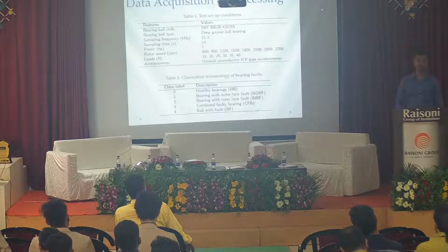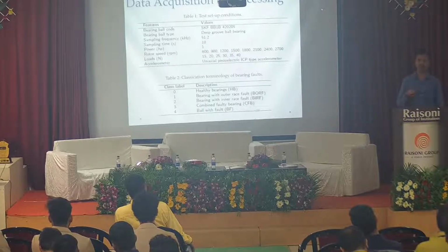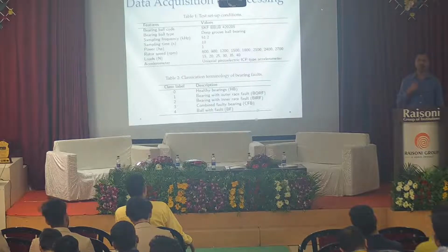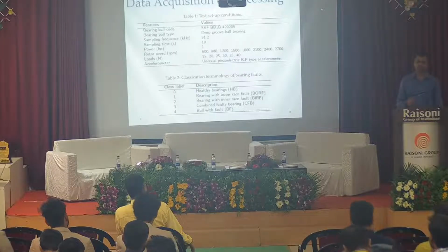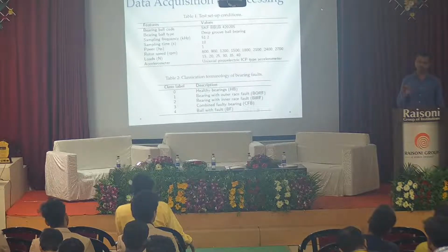In collecting the data set, we need to decide the sampling frequency. Sampling frequency is nothing but how frequently you are going to collect the data. It depends upon the type of application. For example, if you are monitoring the temperature of Jalgaon city, you are not going to collect the data per second. You will possibly collect it after 1 hour, or in the morning, afternoon and evening, because the application is not that sensitive.